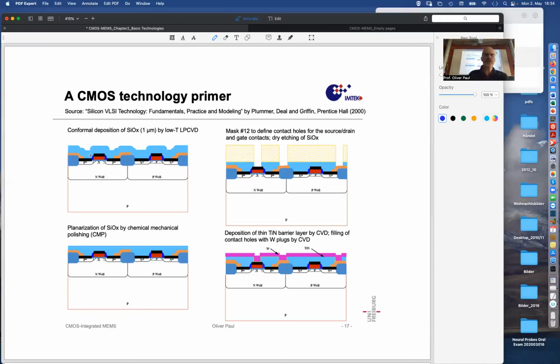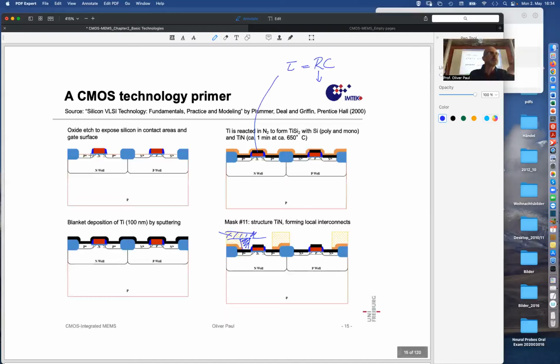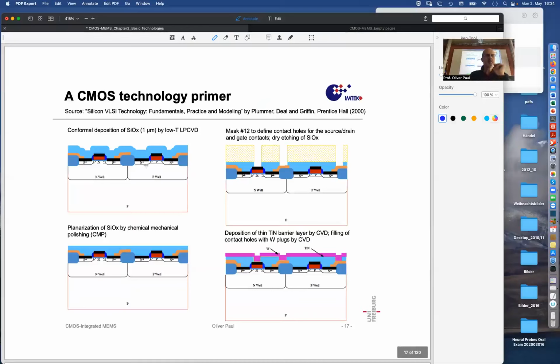And that has again to do with this sidewall spacer idea. We have created this sidewall spacer by having some anisotropic etching and some topography. And now if you imagine that you have this topography and you deposit a metal layer as a conducting layer that you would like to structure, if that etching is two directional, you may have some leftovers of metal along those steep walls.